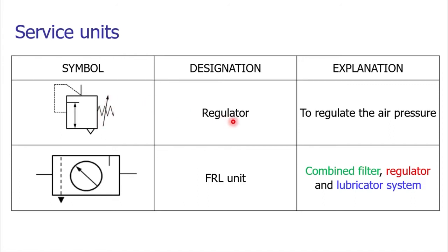When the system pressure increases beyond the critical pressure, the set pressure, or the cracking pressure, the compressed air has to be vented out, sent to the environment. For that purpose, a small open triangle, not a filled-in triangle, is at the bottom side, giving the indication that the compressed air has to be vented out.